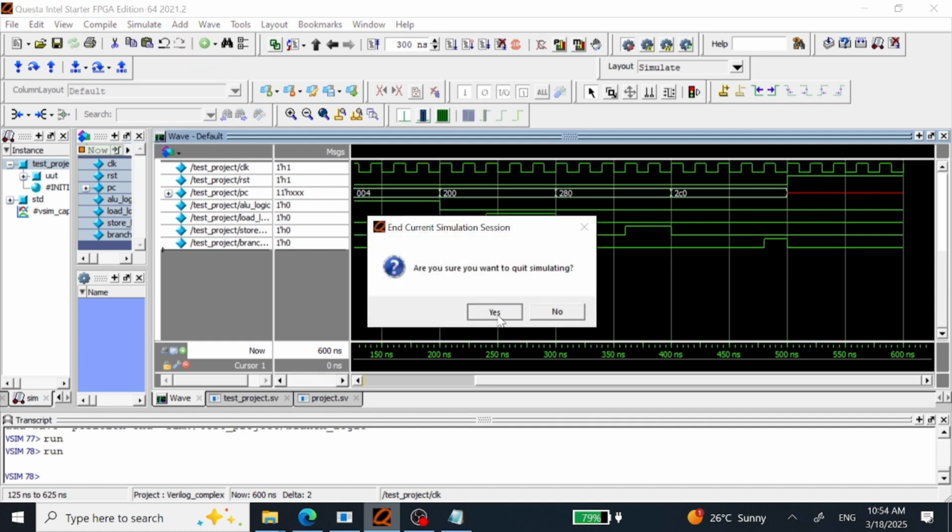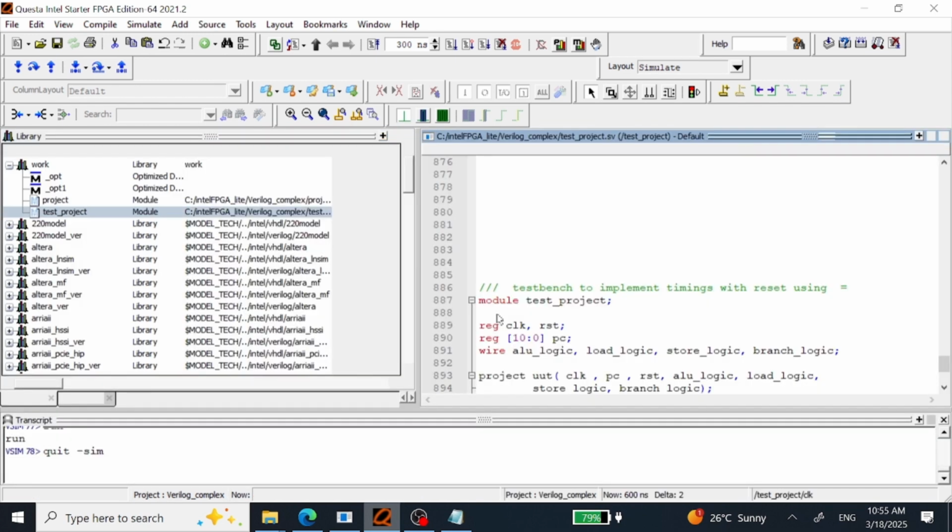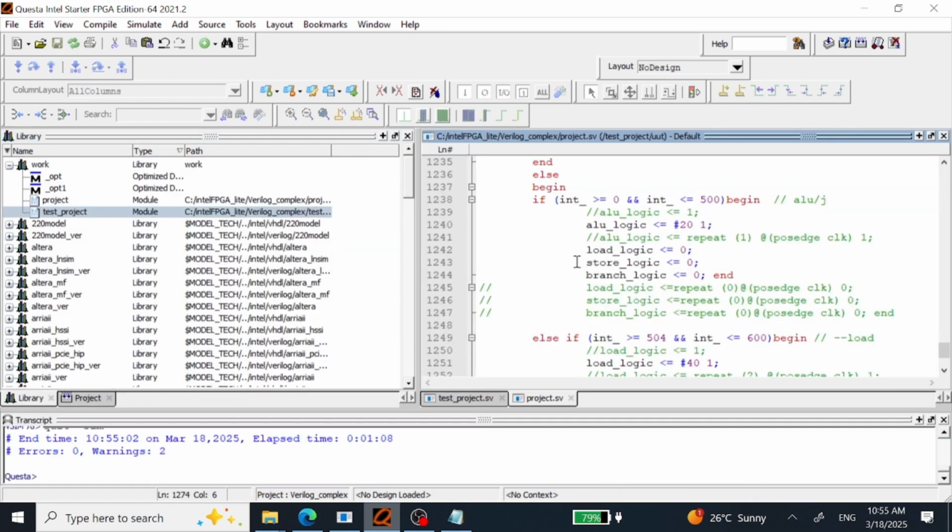And now we are going to see how we can give these delays not with the time units, but with the number of clock cycles. So what we are going to do is comment out this line, include this line. Using this repeat keyword, we are going to run this on positive edge clock once. So this is going to give our 1 cycle delay according to the clock cycle. Make it 1 this way, right? Others are going to stay same.